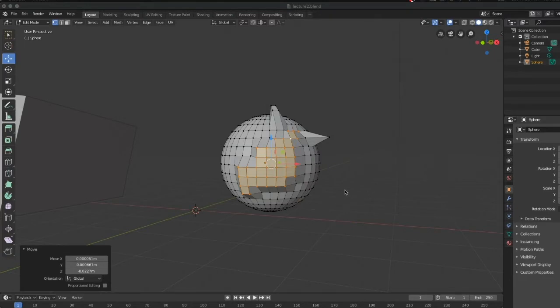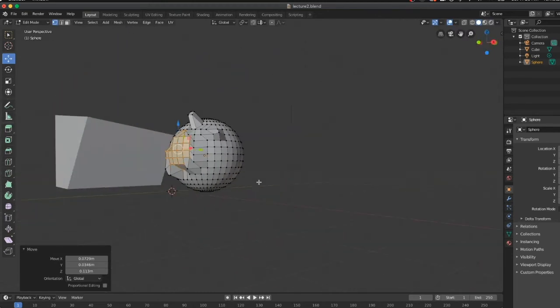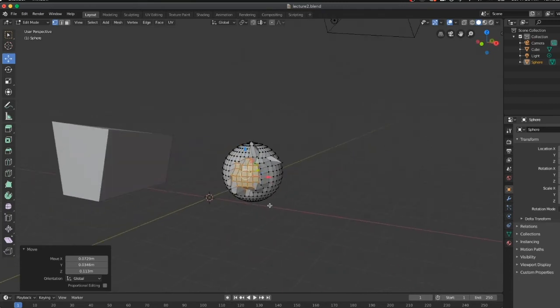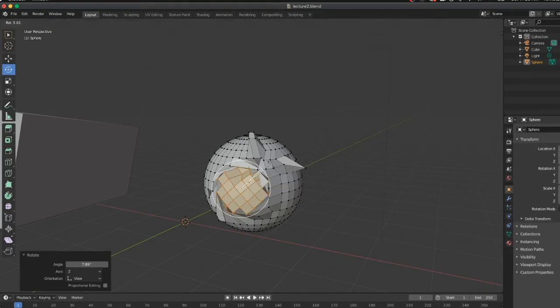You can use the C key with the G key. So I'm going to go back into my object, deselect, go to my C key, highlight some, then I'm going to hit my G key. I have to hit escape and then hit my G key, and that really lets me grab this. It's very helpful for selection of large objects, not so much little tiny UV spheres. Okay, that's pretty cool, and you could see maybe why you would want to get in there with some specific actions. You can rotate. You can scale. You can do all of these cool things in your objects. It's pretty useful.